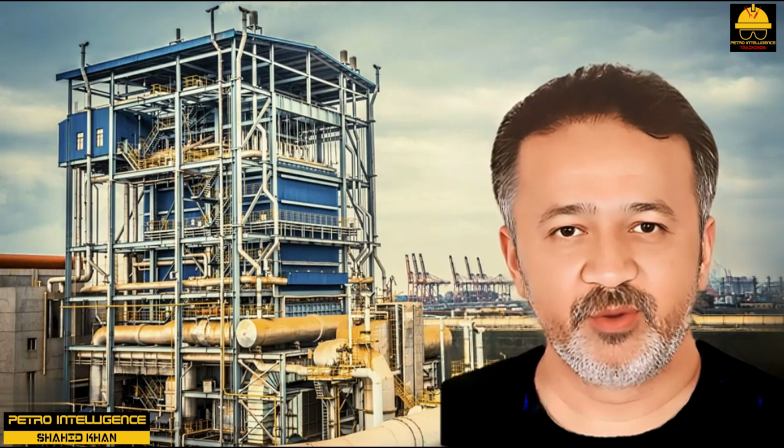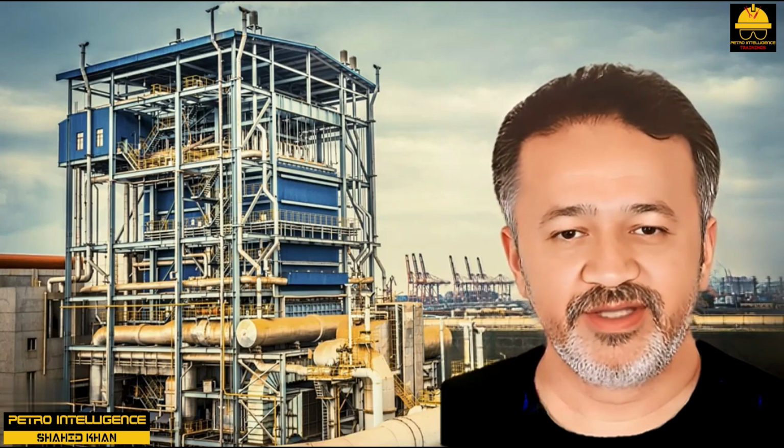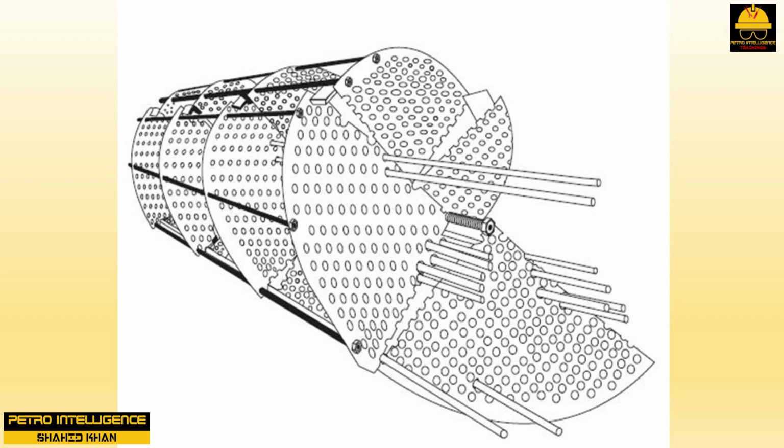Helical tube support baffles. Tube bundles with helical baffles are now produced by both ABB Lummus Heat Transfer and Koch. HTRI now has a rating for this type of design option in their software. Although the traditional shell and tube heat exchangers have segmental tube support baffles at 90 degrees to the line of the tubes, the helically baffled tube bundle has tube support baffles sloped so as to induce a helical flow pattern on the shell side, shown in the picture.